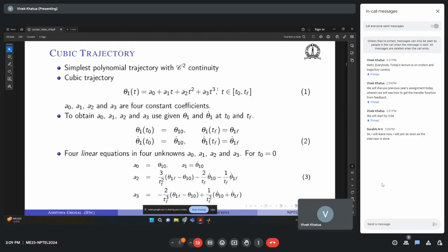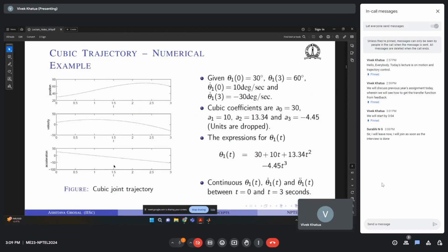So you would require a third order system, right? This polynomial is of third order, and with this you would have our acceleration. You can see acceleration is linear. It can be constant, that is a3 will be 0, and this means that it is a constant jerk that is applied onto the joint rotation. The motor that is causing the joint to rotate is giving you a constant jerk. So that is how you can look at it, zero or constant jerks.